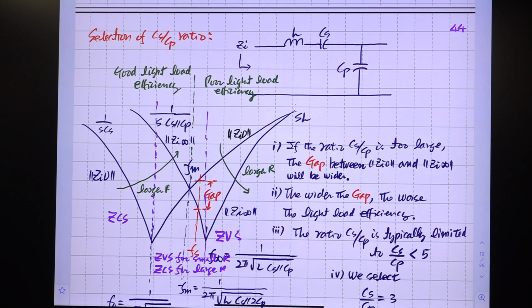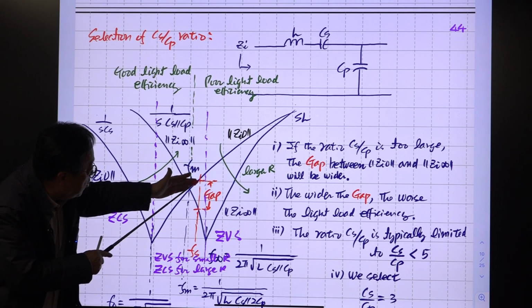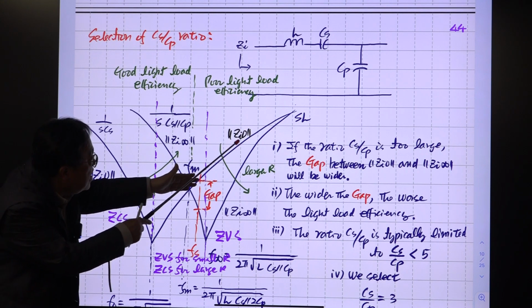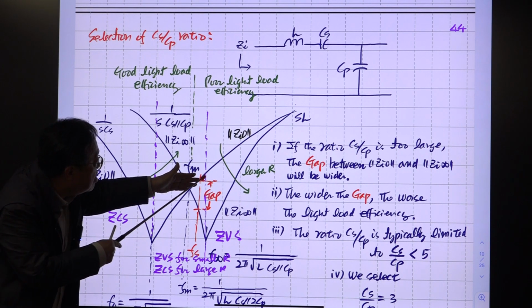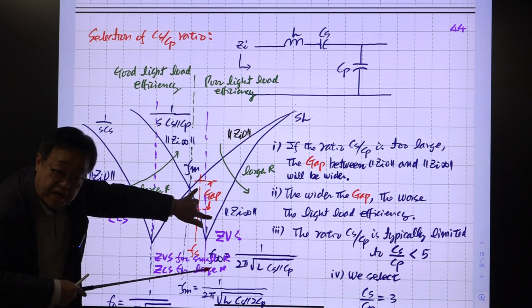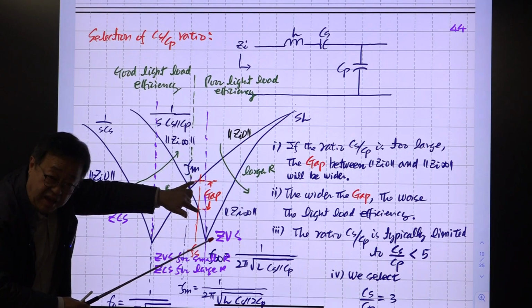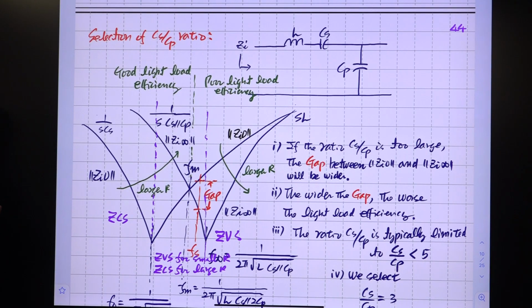That is the very bad case, right? To avoid that case, if you have wide separation here, the switching frequency is somewhere here. Then if you increase this R, this input resistance is decreasing this much. So you don't want to have a large gap like this. That hurts your line node efficiency.